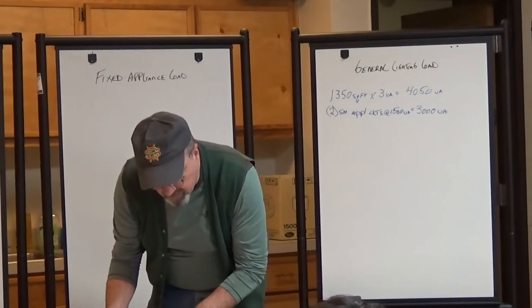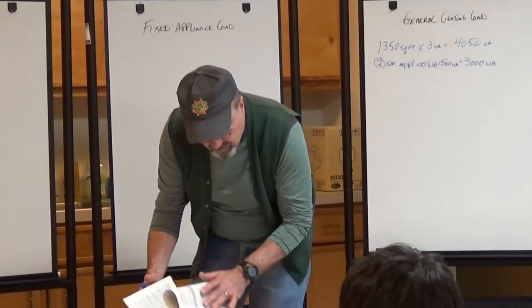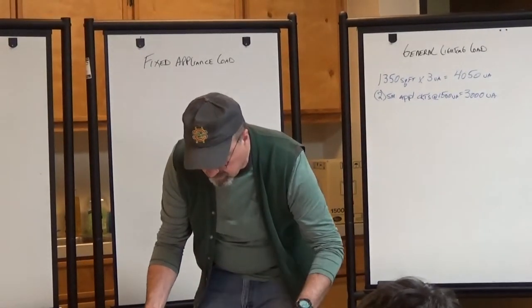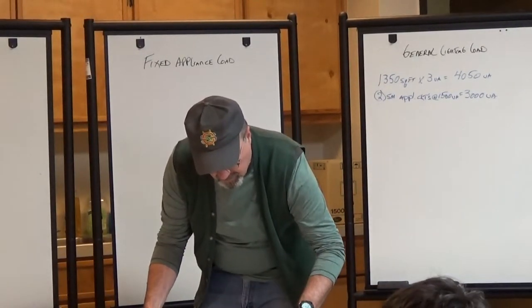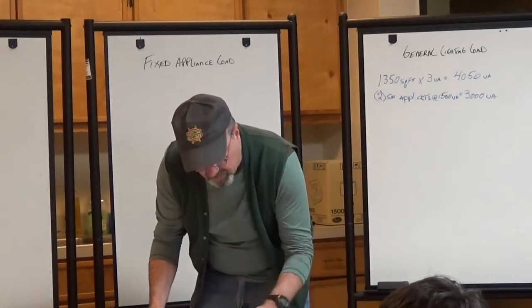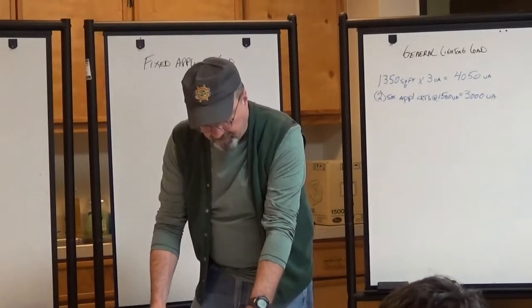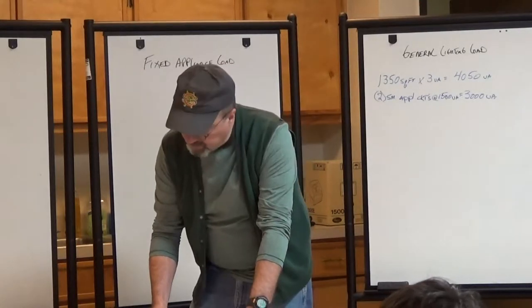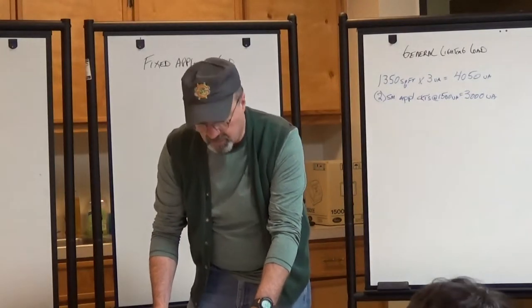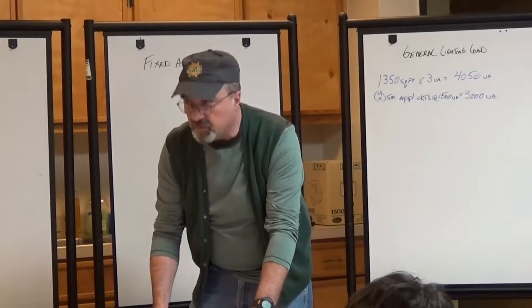Going back real quick to 210.11(C): C1 is the small appliance branch circuit, C2 is the laundry branch circuit.